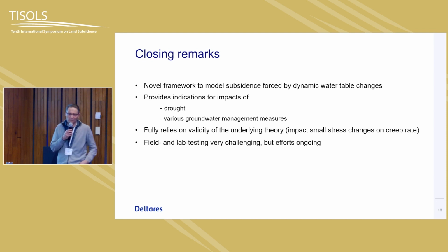If you have a little bit of feeling for this creep model, then you know that, as you saw in the wavy curve, the subsidence is like the creep integrated over time. It's just the rate subtly increasing during low groundwater levels and then decreasing a bit in winter. So that gives you only every year a subtle deviation relative to if you don't have the cycle.